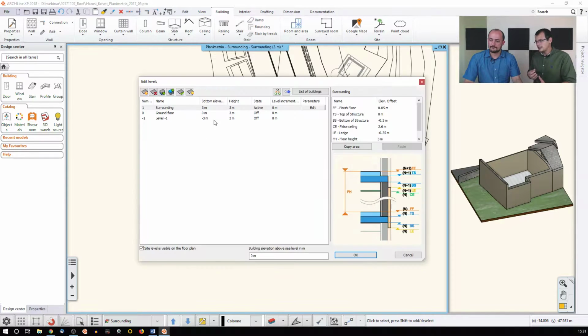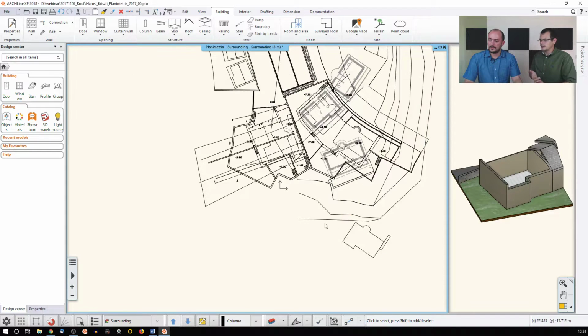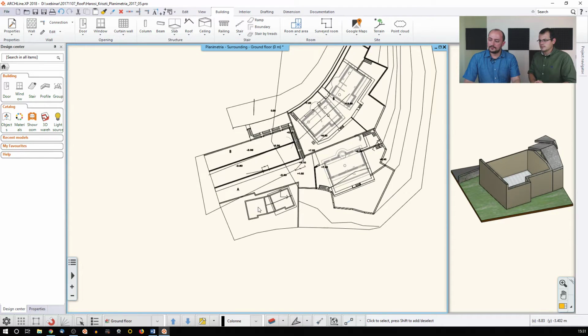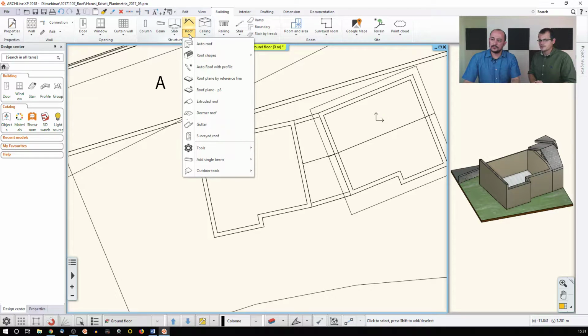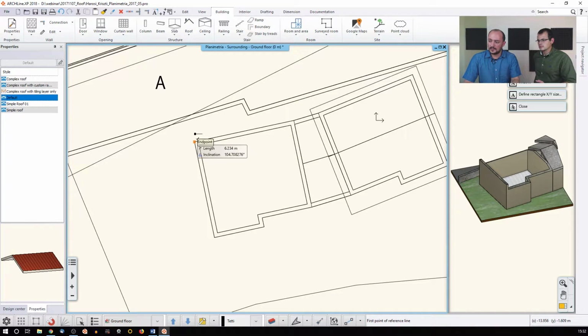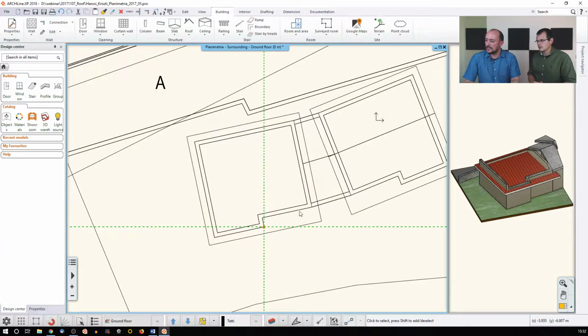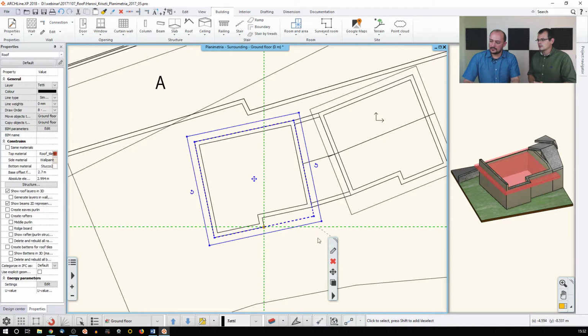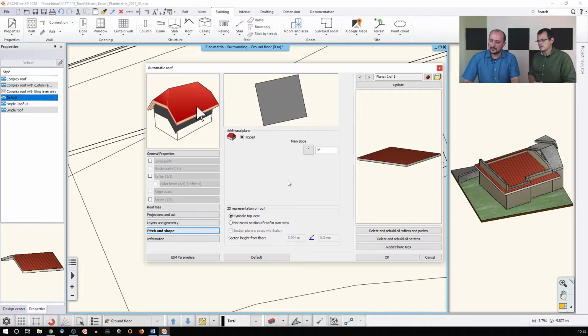And in connection to that, there are a couple of other roof shapes that I think we should show, because they are predefined and you don't have to build them up yourself, but you can use them from the library. The flat roof is designed, just as you mentioned, two ways. There is this roof called the roof shapes, and there's this flat roof. It's really simple. You only need to find the contour which you would like to cover, say the whole building, and then there is a slight pitch in this roof, and just as we discussed last time, you can go to the pitch and shape and change its pitch.